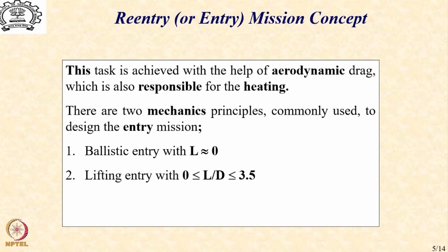As long as L by D is fixed, the drag will be fixed the moment we fix the lift, and if we can control the lift through appropriate control surfaces, we can control the drag. So this is the philosophy of lifting entry. We will discuss a little bit more about this in subsequent lectures.